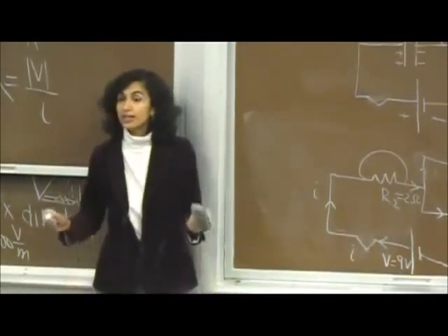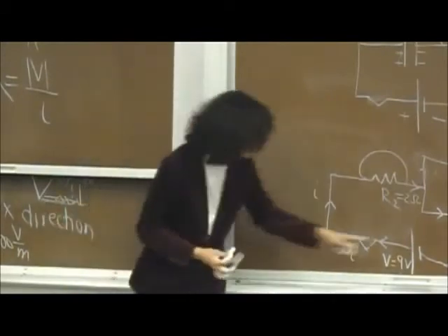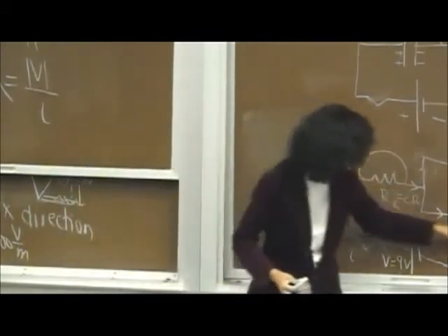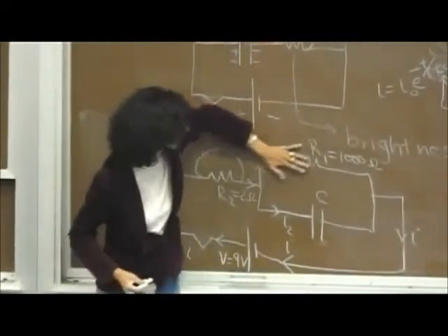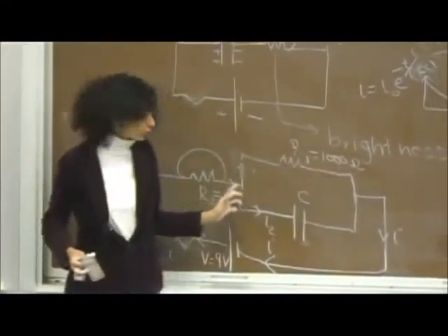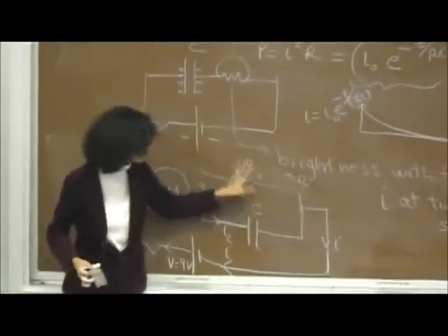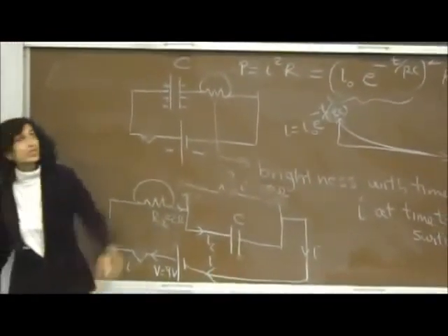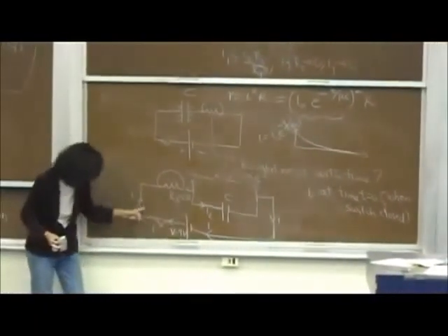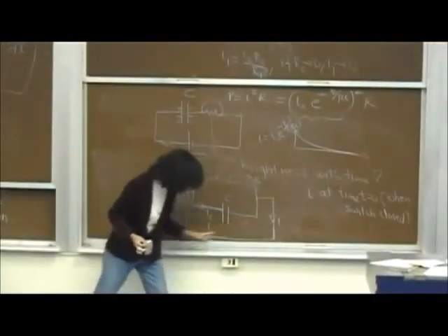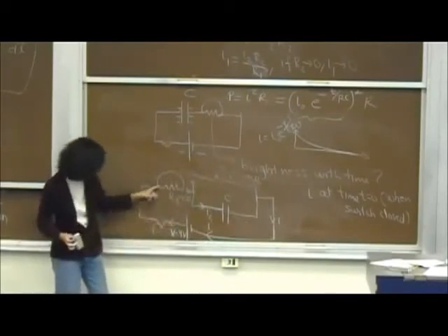Does everybody appreciate that at time t equal to 0, all of the current will pretty much flow through this path? This is like a short circuit, right? So this path will pretty much get shunted out. There is not going to be any current, as though this didn't even exist, just like that one up top. And because of that, how much is the total resistance in the circuit? Isn't this just a series circuit? Look at this.